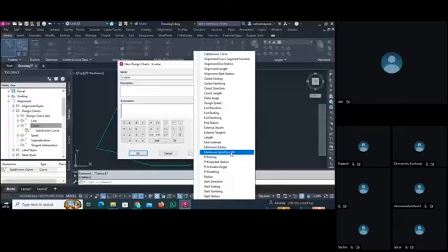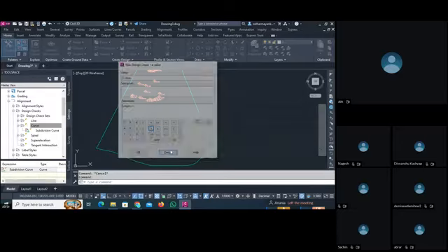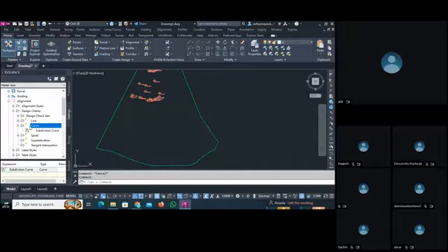So what is the best fit option for this k value? Length is best fit. Whenever we create a curve, the k value depends on the length of that curve, and the k value changes. So we set the length, and we can put any criteria like less or equal or greater or equal, and we add it here. So this will also set.